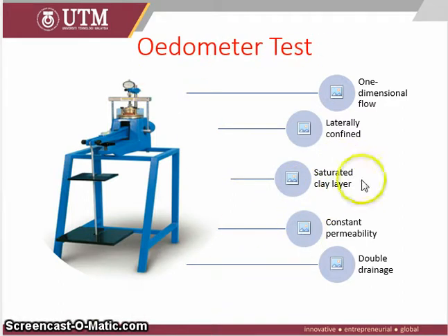So from the oedometer test, by applying the load, it typically takes minutes or hours to complete the test, and from the measurements we can obtain the coefficient of consolidation and also the permeability of the soil.